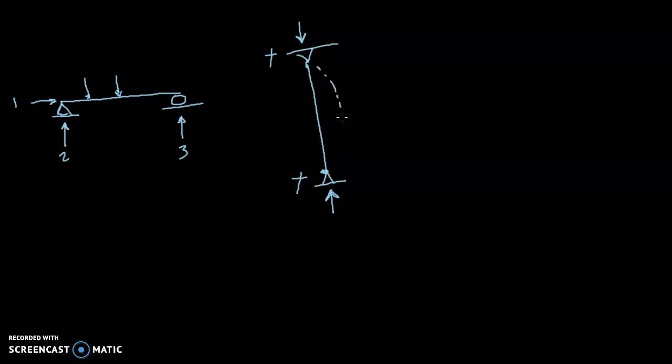Typically, when a certain stress in the column is reached, the column buckles to the side. It bows out. And once that occurs, then you have a force times a distance, and a force times a distance is a moment. So then bending starts to occur and failure happens soon after.